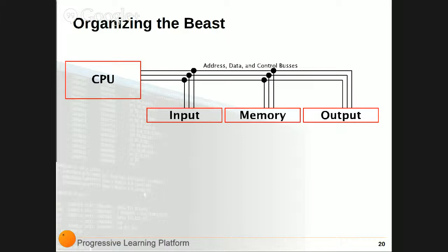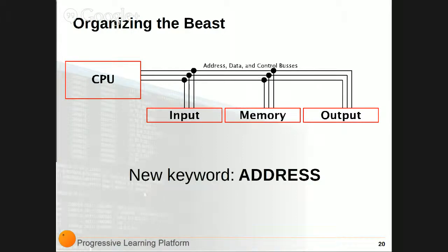What do you think an address bus does? Towards the location of the bits of data. Location. Right? So in your program, instead of loading the value directly or immediately from the instruction, now you have the option of saying, hey, I want to get data, but not from your instruction or program, but from there. Now you have some indirection going on. Does it make sense?